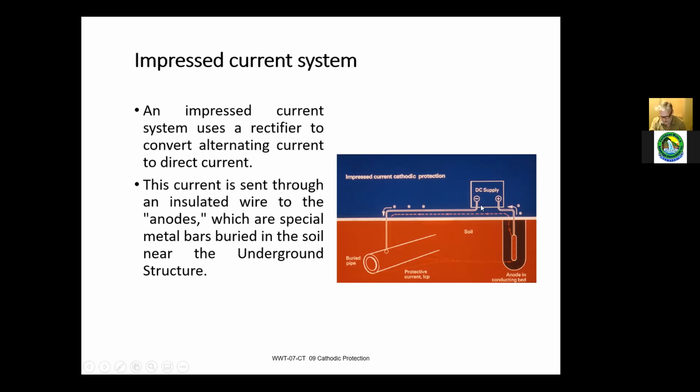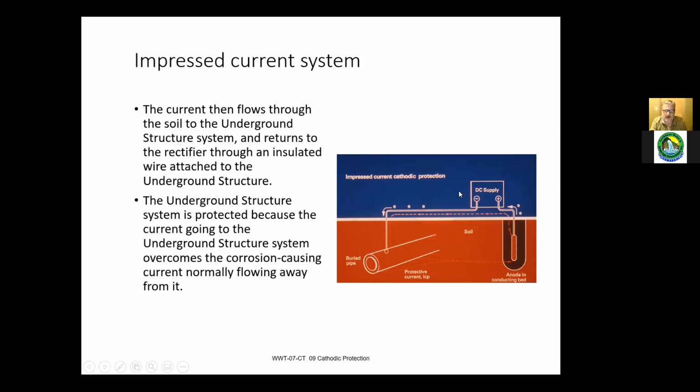So with these systems, you have to monitor the rectifiers. It should be done, we suggest every 6 months or so, but we do it on a monthly basis. You want to make sure that the documents are on site, that the previous readings are available to people when they go out there, because you go out there, see what the last readings were, see what they are now. So that's the only way you can tell if you're getting the protection on your pipe.